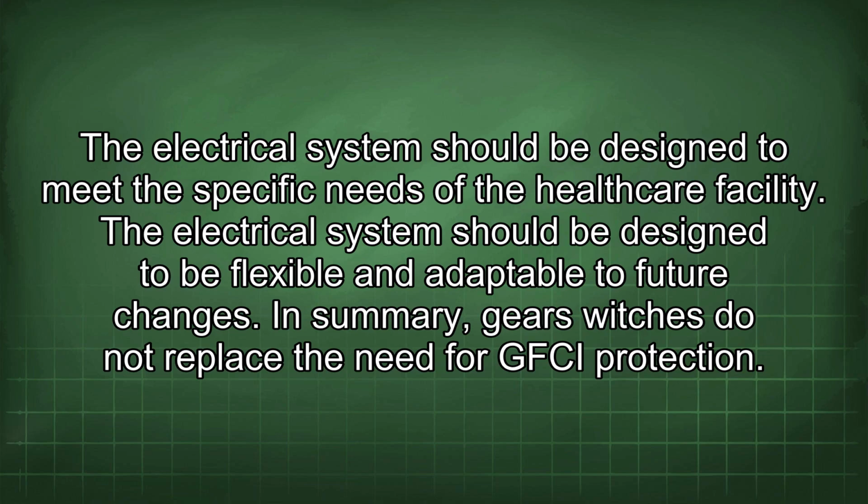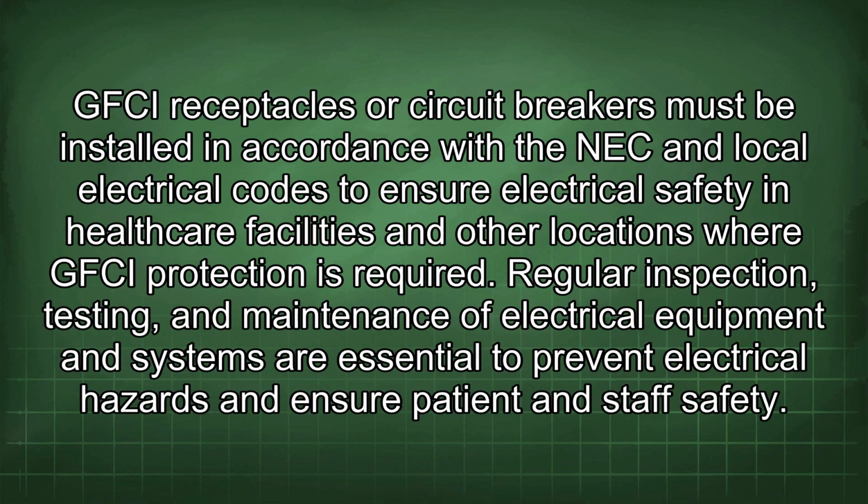In summary, gear switches do not replace the need for GFCI protection. GFCI receptacles or circuit breakers must be installed in accordance with the NEC and local electrical codes to ensure electrical safety in healthcare facilities and other locations where GFCI protection is required.